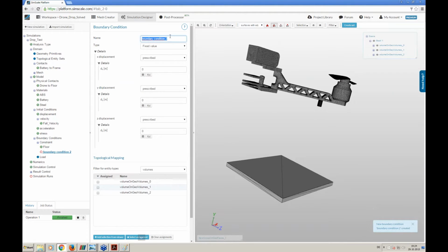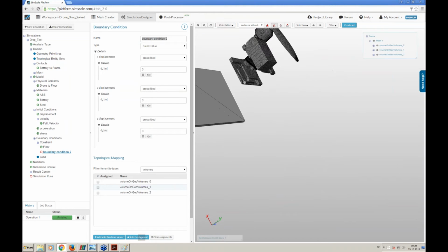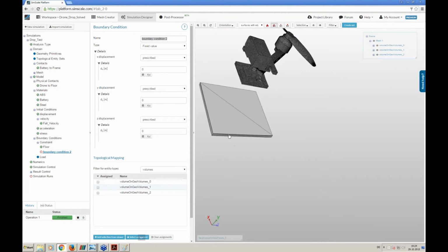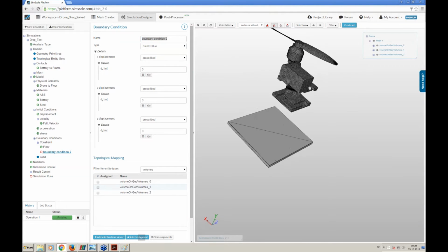Next thing is we will define boundary conditions for symmetry. We have a symmetry plane here and here. And instead of using the symmetry plane boundary condition, we will set up this boundary condition manually, because for such large models, or in general, it's more stable. The symmetry plane boundary condition can cause some problems, and we want to be on the safe side this time.